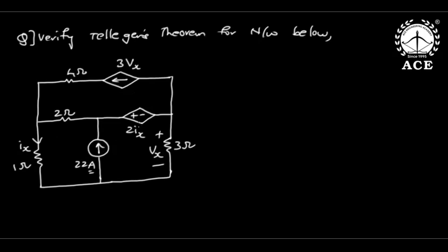Now, what do you do, everyone? Because we don't know how these sources are behaving, whether source or sink, we cannot tell. Resistors are always sink, no doubt. But the independent DC current source and dependent sources, we cannot directly declare. Here you cannot do any reduction. See the second point: topological arrangement should not be disturbed. As it is, we have to prove.